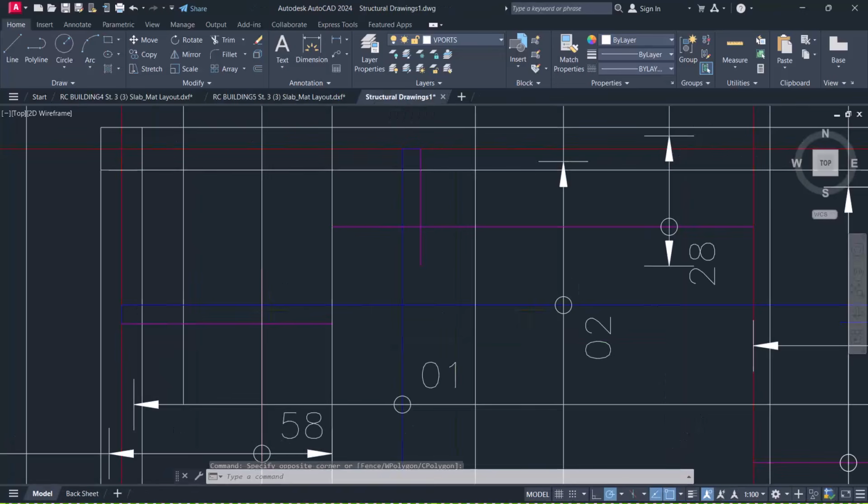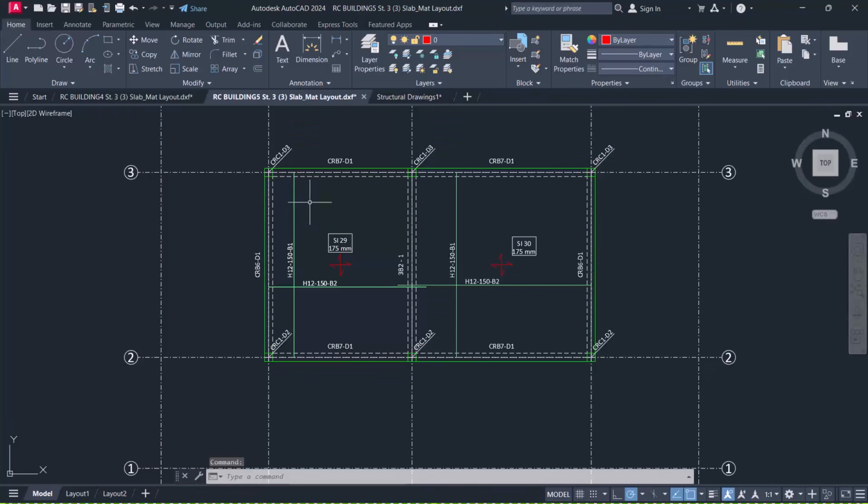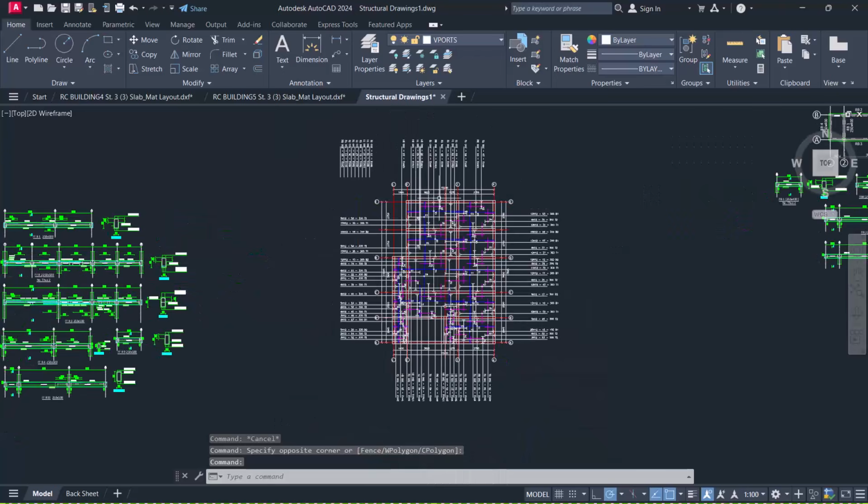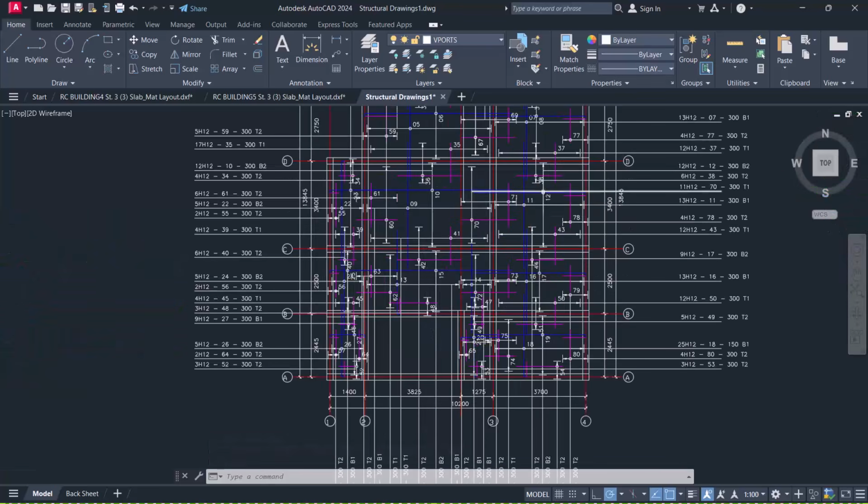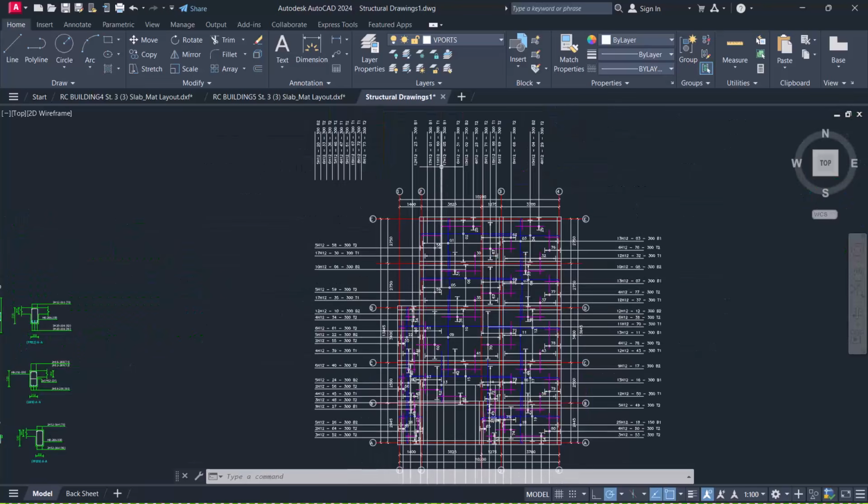So you will need to provide this top reinforcement in these directions and the support top reinforcement, which is this, that we are going to be providing, so as to complete this reinforced concrete slab detailing. All right, and then you provide the center lines and make it more presentable, just as I did here. So this is how you can detail and make your slab reinforcement more presentable.